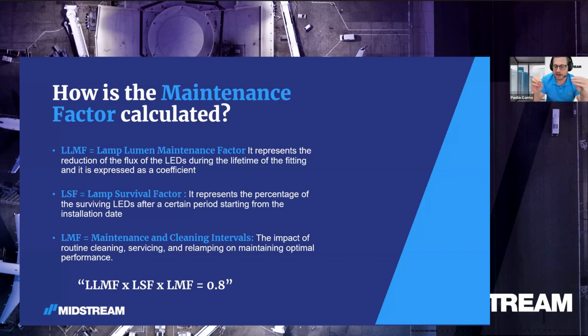So there are standardized ways to calculate, in a perfect environment, how the luminaire will decay over time, which takes into account the LED chip itself, by running testing and projections by the LED chip manufacturers, which then release their data publicly with something called LM80. And then this value is plugged into a standardized calculation called TM21, which takes into account the remaining parts of the luminaire, for example, the working temperature resulting from how well your heatsink is designed.